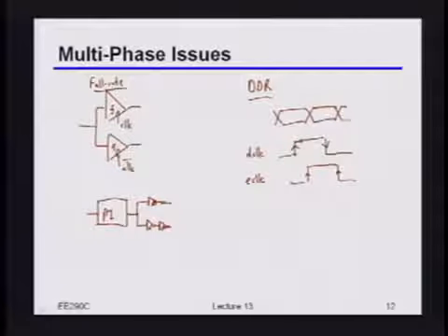Now the question is, how am I going to build this? How am I going to support this in my CDR hardware? And first of all, what are some of the options I might have? Remember that this data clock is not a fixed phase position. It's moving around based upon my CDR updates, and you want that edge clock to also move around the same way. So how might you build this?